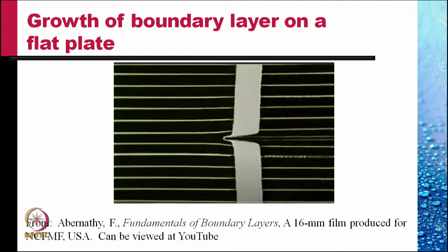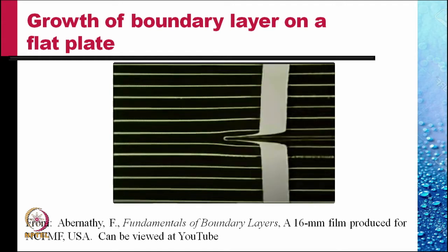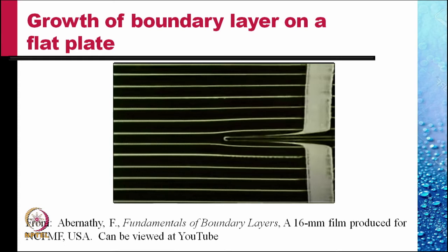At a little later time, the band looks like this. This band is known as a timeline in fluid mechanics. This is at a given time, what does the flow velocity look like? At a still later time, this pattern is this. This shows clearly the growth of the thickness of the boundary layer on the flat plate when that is aligned along the free stream.